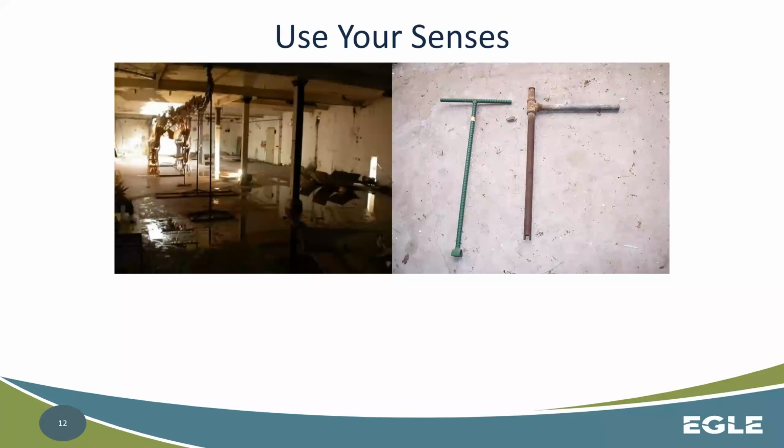The main thing that I would say to meter readers and those that are out in the system getting readings, whether you're driving around in a truck or actually walking across property, is that you're really kind of the eyes and ears of the distribution system. You're the one that's out there day to day or week to week, depending on how often you do readings, understanding what is going on in the distribution system. As you get closer to a home, you can look and see if there's lights on, if there seems to be activity there, or if it's a vacant house. If it's a vacant house and you're walking through property, you can maybe look at meters, listen for water leaks, look for daylighted water.